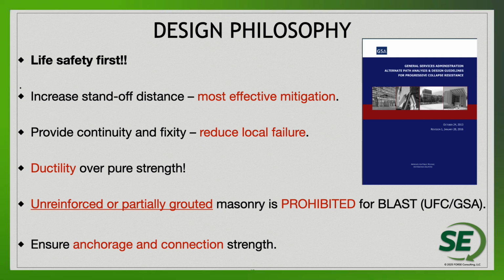The most effective blast mitigation is increasing the standoff distance, and continuity and fixity matter more than absolute strength. Connections must really be robust because failure there negates basically all wall capacity, and load distribution in that case would really result in collapse.